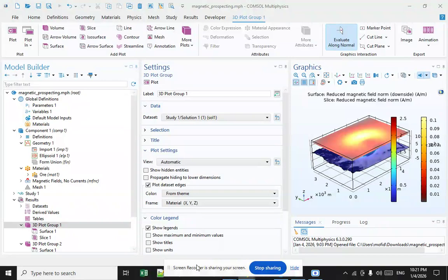The background magnetic field is assumed to be uniform within the simulation domain. Intensity and orientation of the natural magnetic field is estimated using data from the National Geophysical Data Center of the US government, and this application neglects the induced and remnant magnetization of the rocks outside the iron ore body.